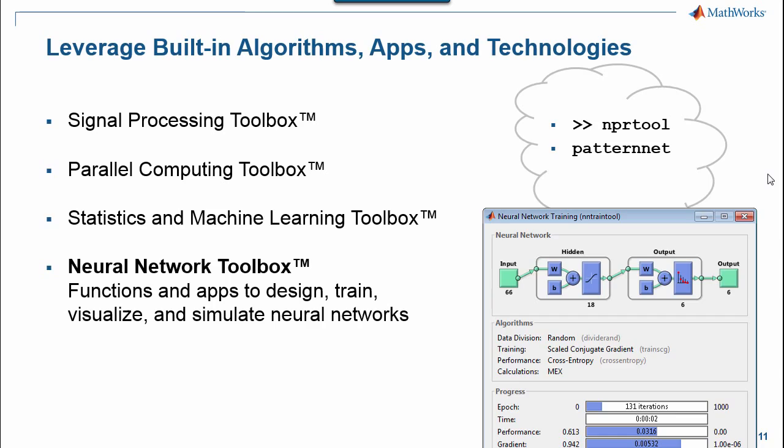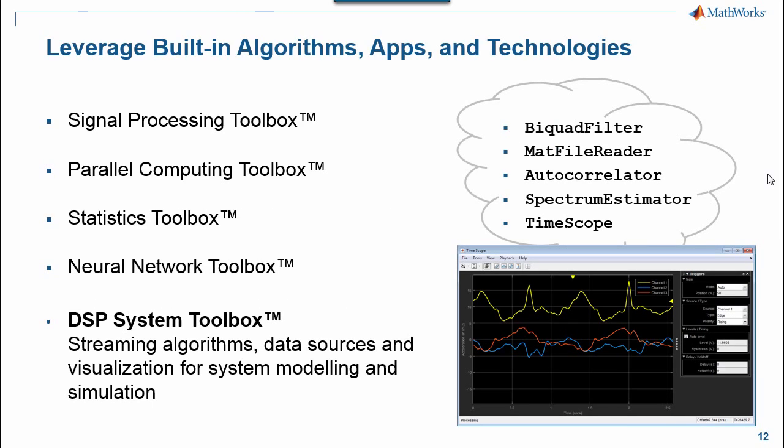With the fundamentals of our signal processing algorithms already consolidated, we used a number of objects from the DSP System Toolbox to model the real-time implementation of our algorithms. We ran an online simulation of our system design using objects that facilitate the streaming of data from long signals stored on disk, and we used scopes that are optimized to handle the continuous visualization of streamed signals, similarly to how one would visualize a real-world signal with a benchtop instrument. As a side effect, our online modeling efforts made our algorithms already a lot more efficient to execute in simulation, and also made them ready to generate C or C++ source code that could be directly deployed onto an embedded processor. And that's where we used MATLAB Coder.